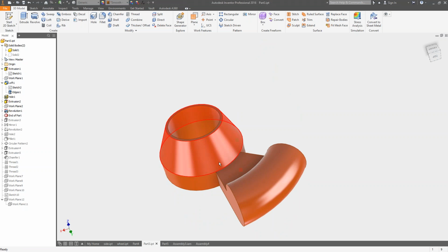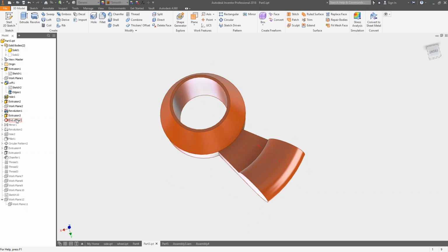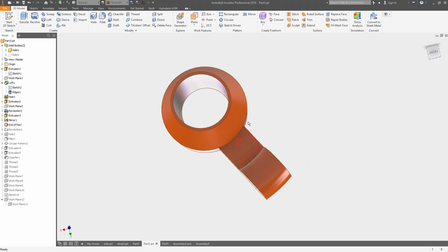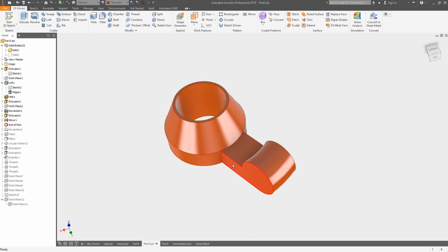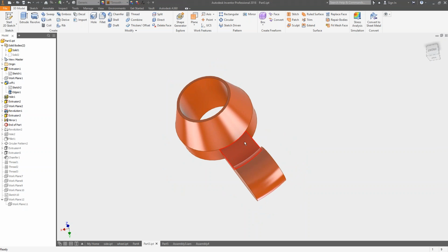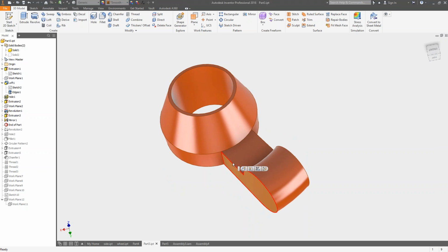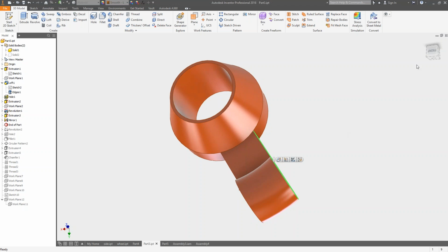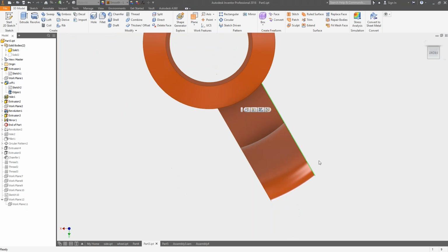From there, I revolved from one side to another. I squared up my edge, mirrored over to the other side, because I wanted these to be parallel, and this is why this was a tricky model here. I wanted this face here and this face here to be parallel, but if you look at this, that's a curve right there. So that's why I did this as like a 2-step operation. I revolved it first right there, then I basically cut it away and made those 2 faces parallel.